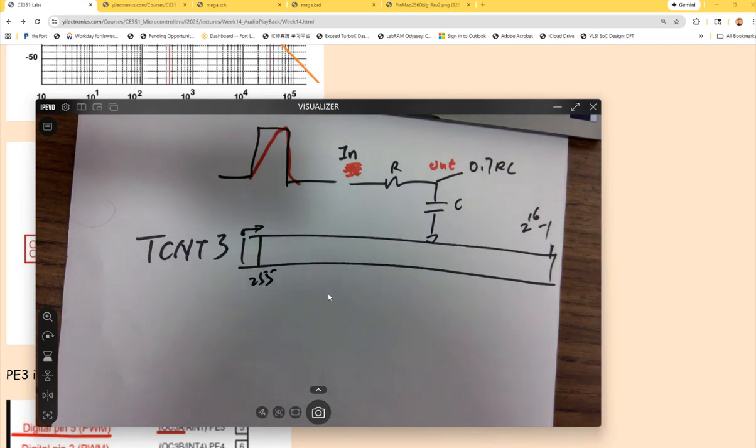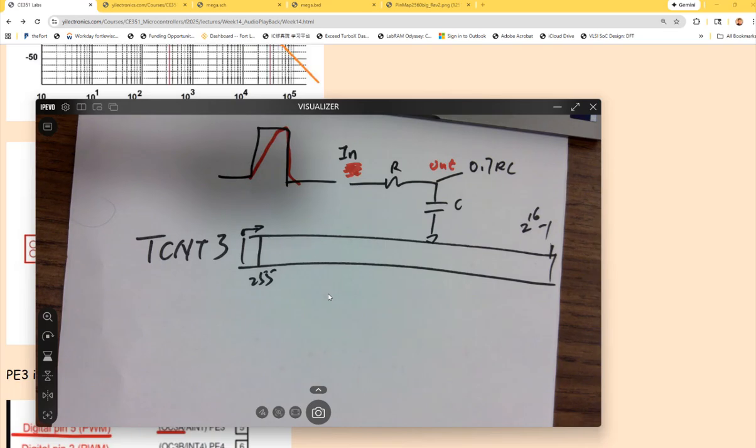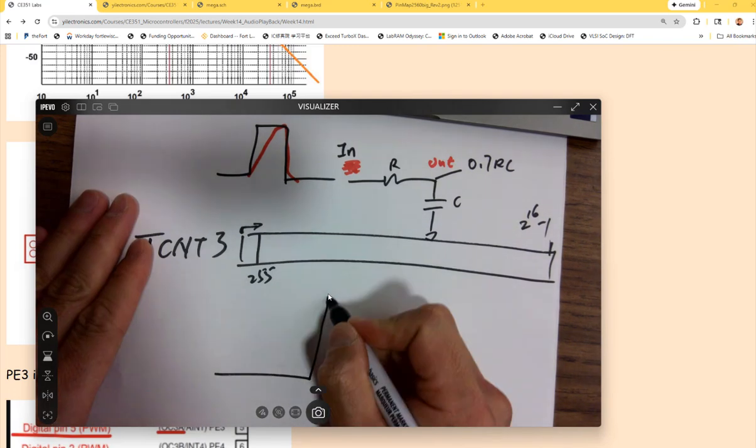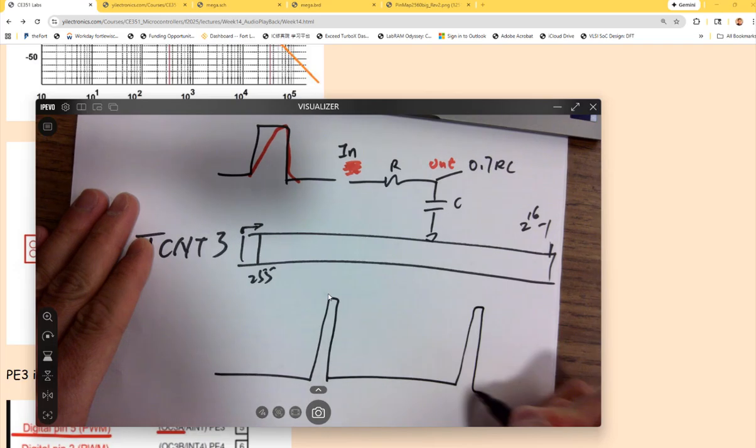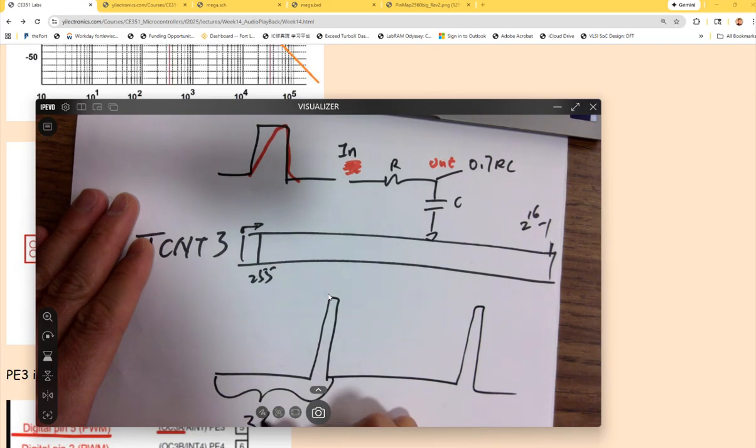What did we use last time? I think that was like 400 or 399 or something, right? So we picked that one to define the frequency of what? Of the PWM for IR, right? Remember the IR requires 38 kHz?